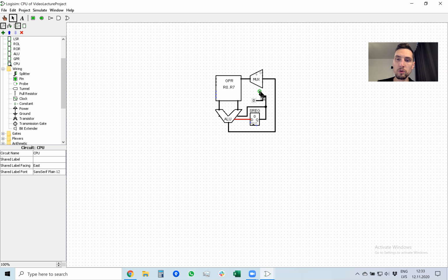And here out goes the combination of these two 4-bit nibbles, which is 8 bits, and I can connect it directly to the general purpose register. So the top 4 bits will always be 0, and the bottom bits will be taken from the status register. So for example, in the status register, if I write F, which is 4 ones, then 4 ones go in, and here the top part is just 4 zeros, so 4 ones is 15, or F in hexadecimal.